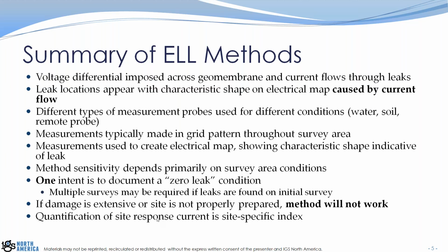So the site response current. One thing it mentions is that it's site specific. So a 20 milliamp current draw with 500 applied volts at one site might mean no holes, and it might mean 2 holes at another site. So it's very site specific.